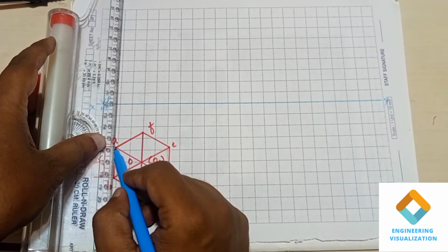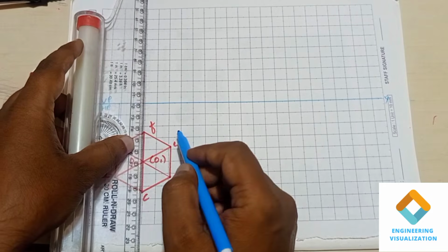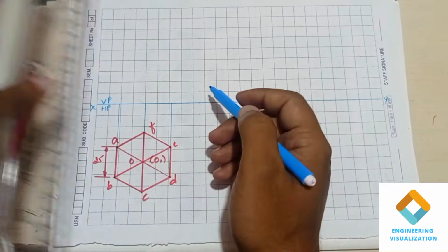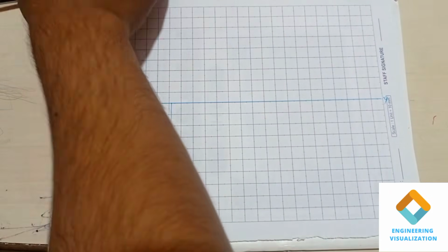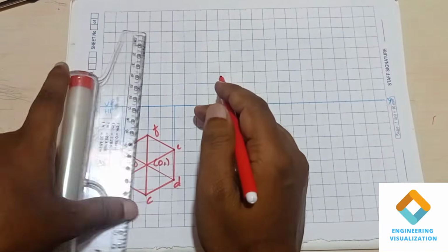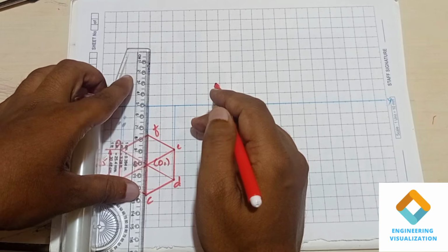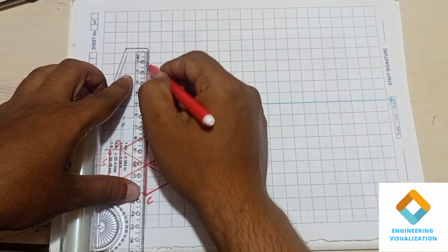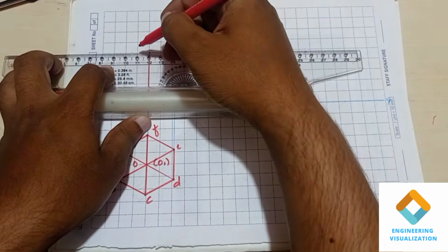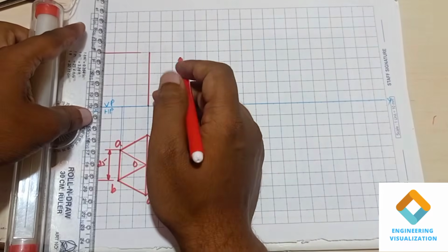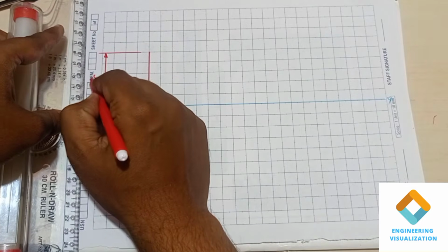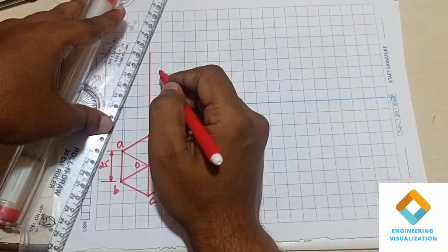Now draw the projection lines upward to draw the front view. So the front view of the pyramid, it is a triangular face. Okay, the axis length given it is 50 mm. So draw a vertical line for a length of 50 mm. Here axis is not visible because the slant edge is covering the axis. So that's why we draw the continuous line here. Show the dimension of 50 mm. Okay, draw the triangular face.